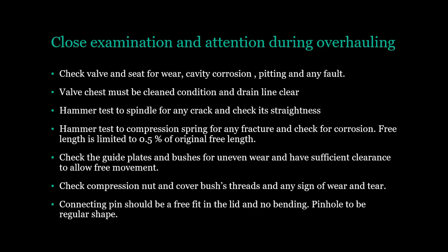Check the guide plates and bushes for uneven wear and have sufficient clearance to allow free movement. Check compression nut and cover bushes, threads and any sign of wear and tear. Connecting pin should be a free fit in the lid and no bending. Pinhole to be regular shape.